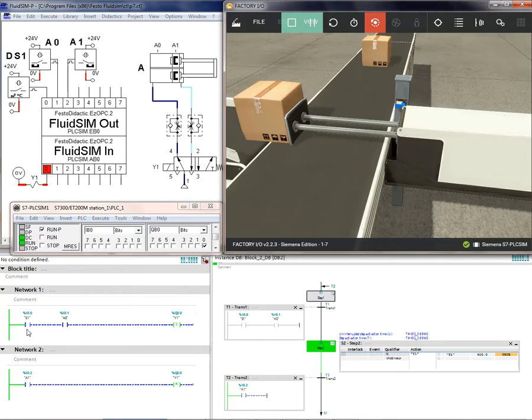In the ladder language, diffuse sensor 1, as you can see, detected the box for a short time, and the Y1 is going to be set. When Y1 is set, the cylinder goes out, or A plus.